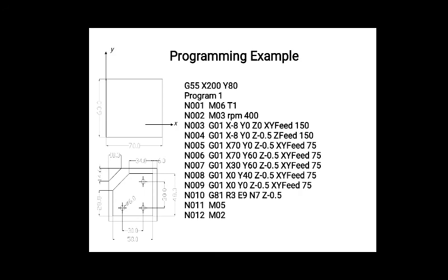If you observe here, there are three main parts in this programming. Okay, first is the program setup, that means we do the tool change, spindle movement in clockwise direction, its rpm. That was the first part of any programming. The second part is the chip removal or the cutting operation, which is performed over here.